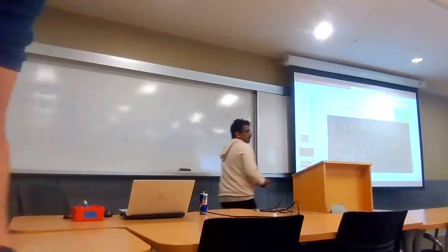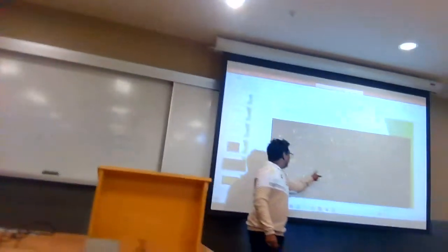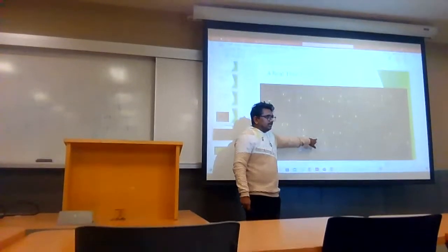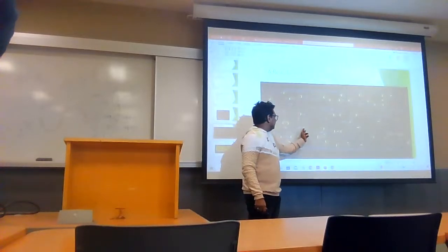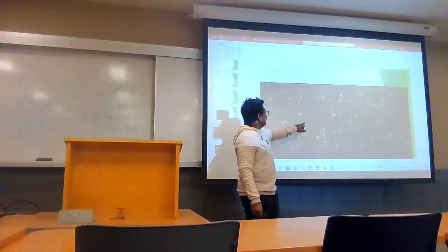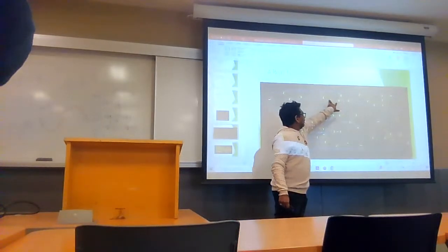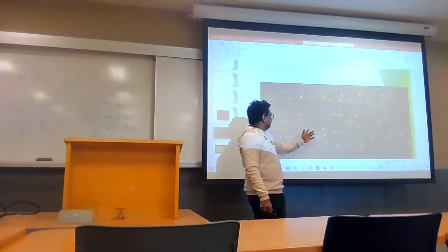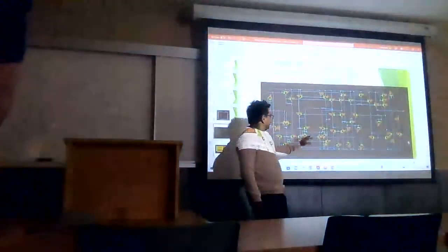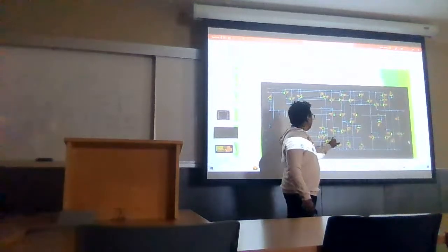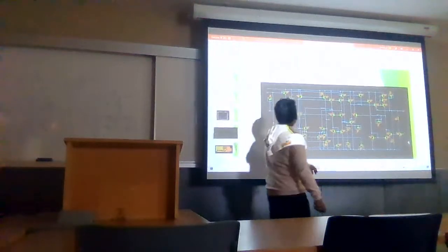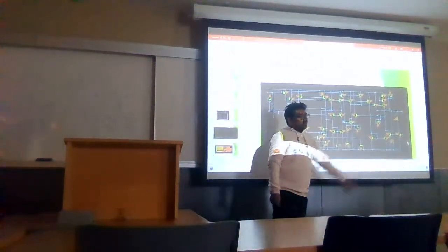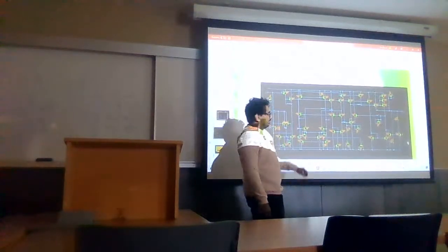Okay, whatever I discussed right now, you can see this is the differential pair here, and this is the folded cascode, and you can see this tail current source. This is some two current mirror. This is not the two-stage op-amp I discussed; this is another architecture. It is a folded cascode op-amp, and you can see the current mirror here, and the performance of the entire circuit.